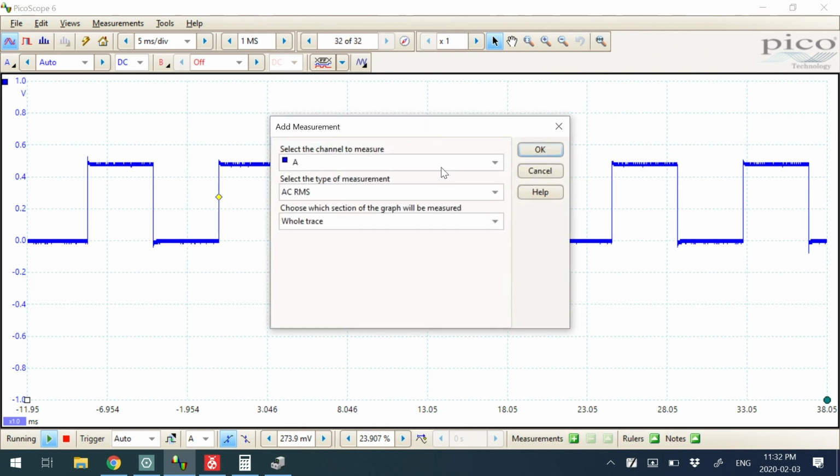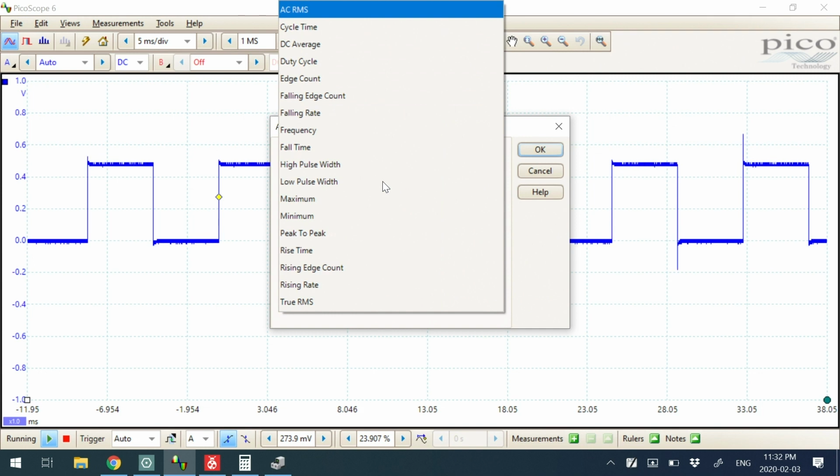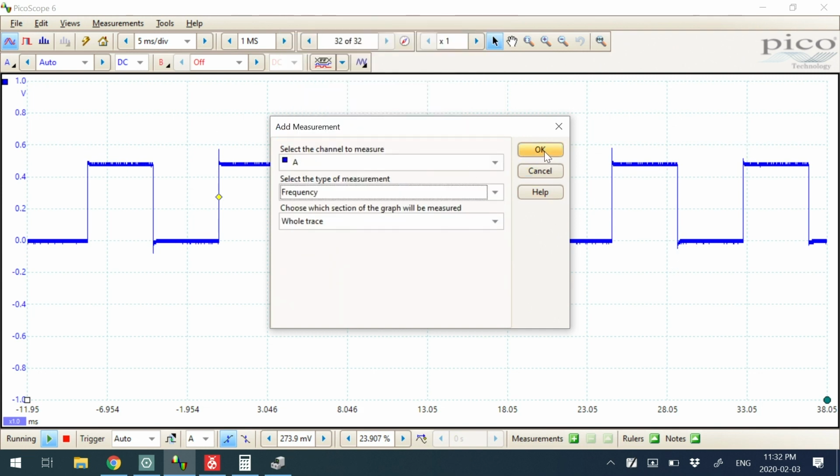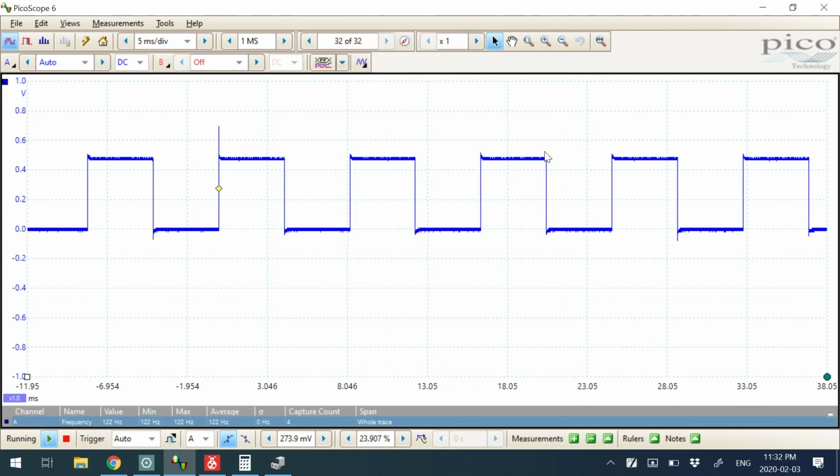Well, it's actually probably going to be half of that. Let's see if we did this right. Or no, double. Because what's happening is, it's transitioning, I believe, on the 61 hertz point. So it's toggling. So we see we have a frequency of 122 hertz, or this is running at 8 megahertz. Either way, it gives us a starting point here.